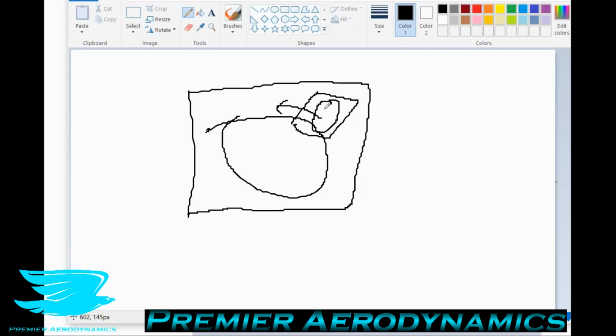And what we do, we move this rock with this mesh, and all the values that are calculated on this mesh then get transported onto the global mesh, so this first big mesh. And so that means we can move this entire object around and still simulate our domain, because the values calculated on this mesh are still calculated wherever it is in this bigger domain, and these values are just imprinted onto this larger domain, and we can then use these values to understand how the entire flow in the entire domain is. This is what an overset mesh is. The great thing about overset meshes is that you can have as many as you like. So you can have another rock around here if you like, and have another overset mesh, and just have them moving around. So that's very powerful.